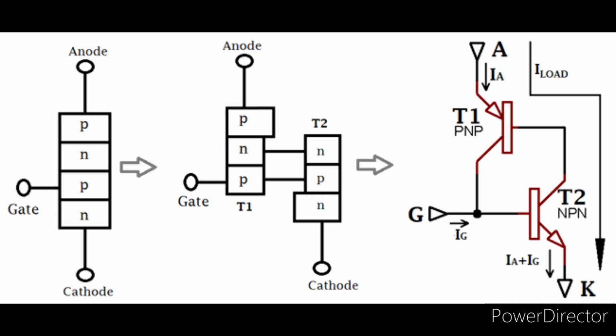So, in applications such as alarm systems, we cannot use transistors, but we can use thyristors. But for applications like audio systems, we use transistors but not thyristors because we need continuous control over the amount of current flowing, because we need to track variations in the sound.